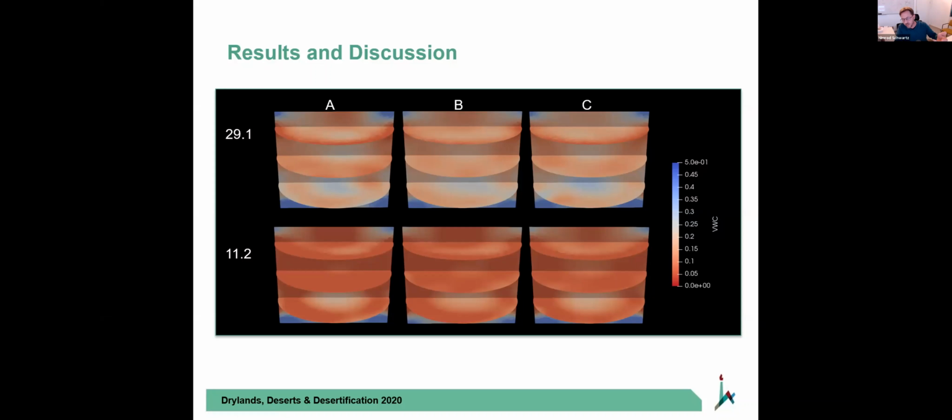Yeah, so the electrical resistivity tomography, we measure or we map the electrical resistance, and using the TDR, the data from the TDR, we translate resistivity into water content, and this is what you can see here. So you can see that the soil dries out, and those red colors here. So the soil, of course, dries out.